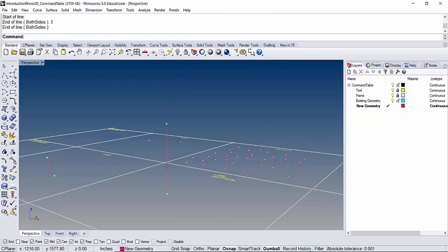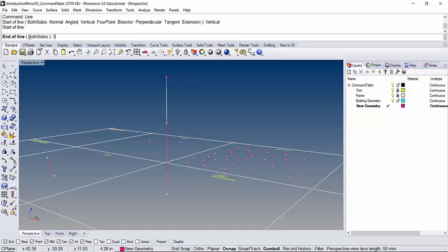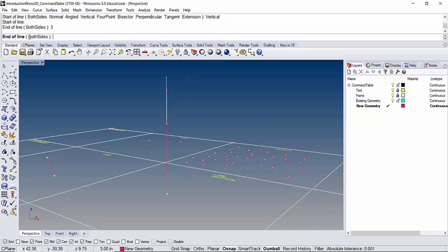I'm going to click again. If you want to repeat this, we can do this multiple times. So let's type line again, select vertical, start of the line, we're going to type 3, and then you're going to right click, and that line is now locked through 3. So you can either use 2 points, or you can use a starting point, set the vertical, and now that's going to be locked to that direction, but with that amplitude. Any questions about this?